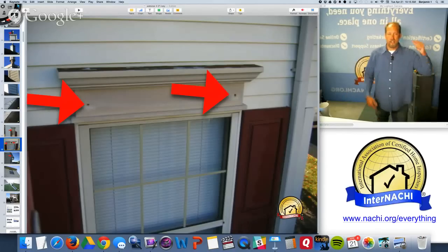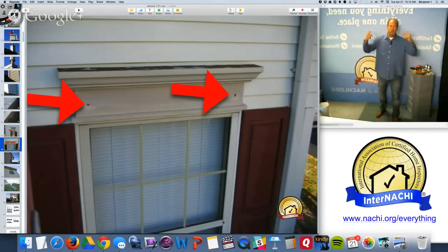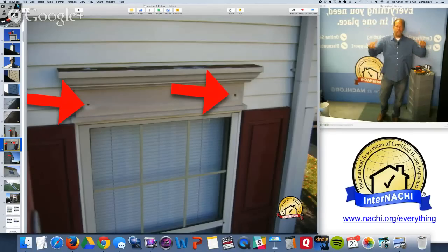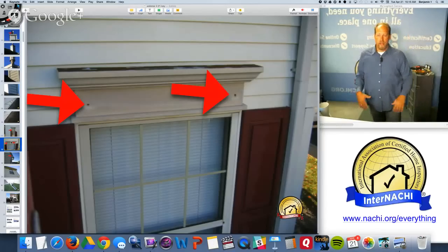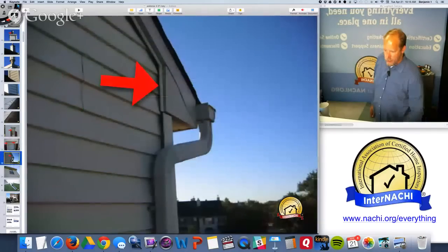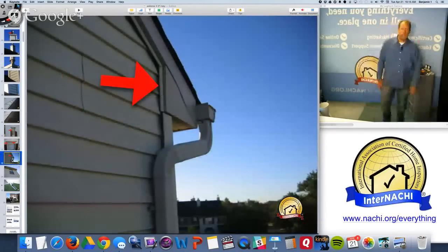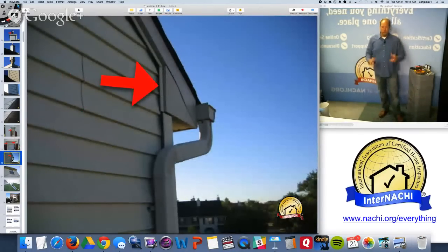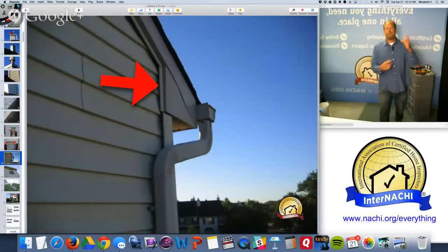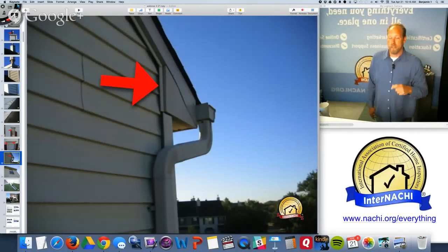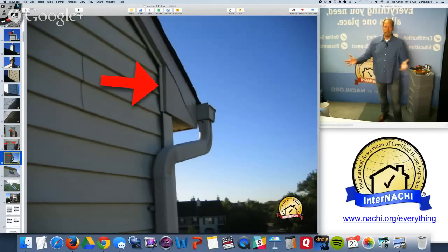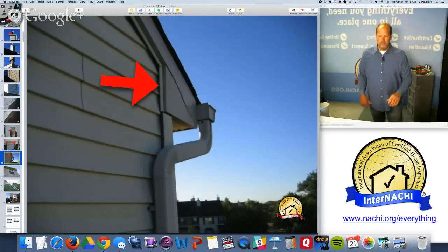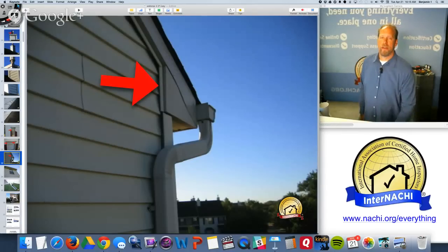So I'm looking at the top, left, and right corners of every window, every door, looking for header flashing, sealant, openings. Things need to be shedding water away, and that usually pops up a lot of things. So I take great consideration with my camera of all the details. If I force myself to take hundreds of pictures, of just about everything, I'm forcing my eyes to follow my camera lens and what it's focusing on. And I pick up on stuff. So I want to make sure that the aluminum capping, even at the corner of the structure, is done properly.